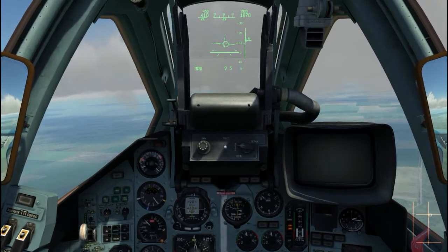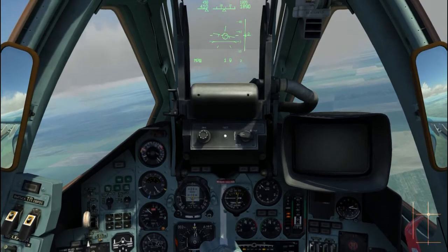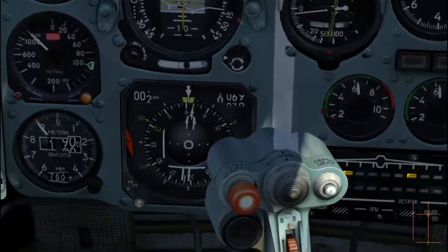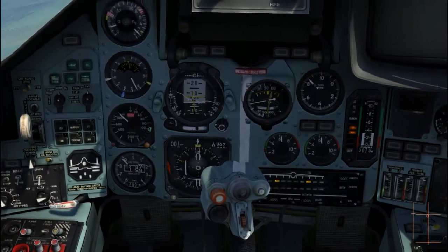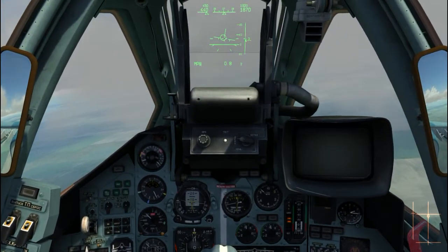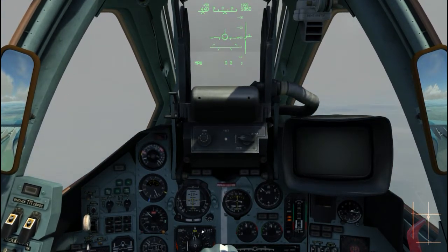Okay, so now we're pretty much on the course line and almost at altitude. Just need to adjust it a bit. You'll see the yellow needle on the HSI swing to the right and keep pointing at the waypoint as we pass it, until the next point is selected.